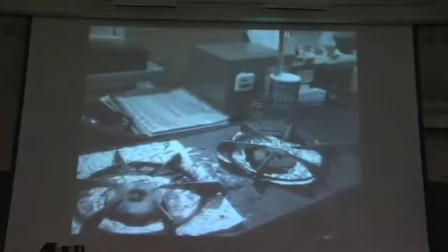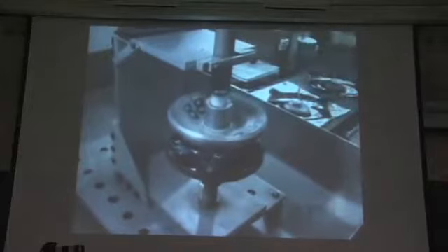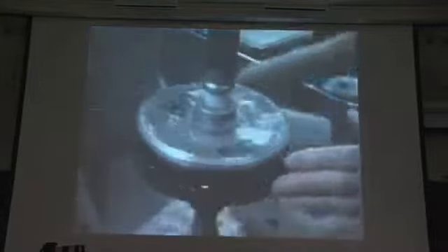A worker picks up a hot aluminum dome called a blocking body. He presses it onto the pitch-covered lenses, and the pitch melts onto it. Dousing it with water causes the pitch to harden, sealing the lenses to the blocking body.